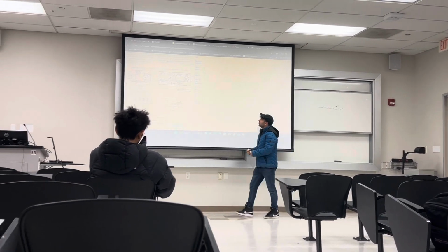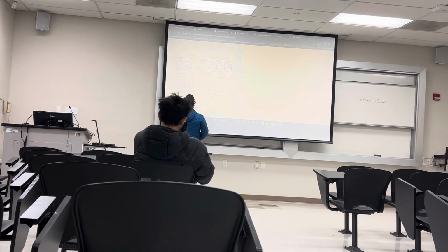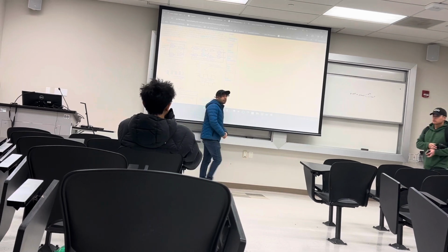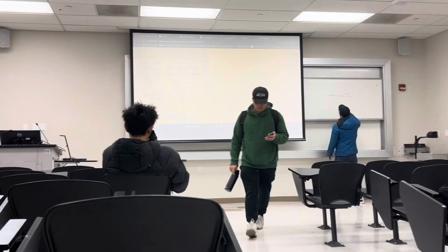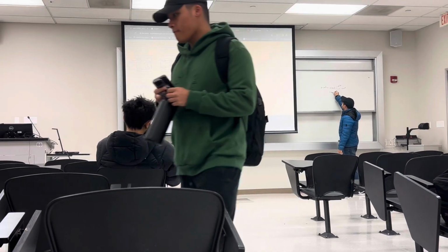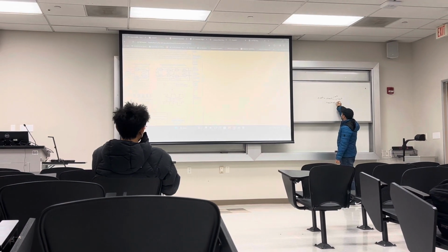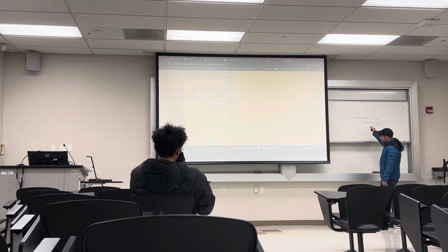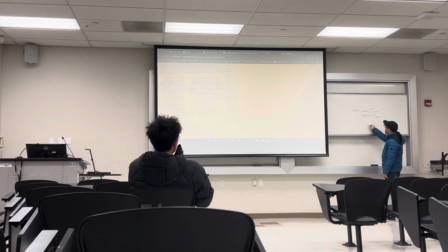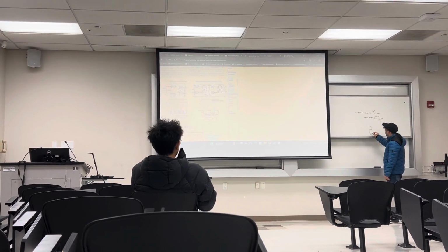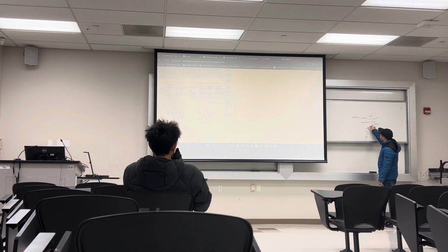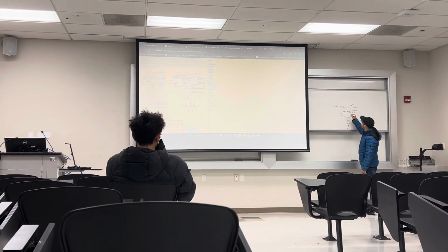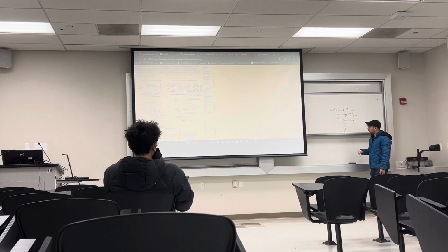The only difference is that here you also have some NAND gates with 3 inputs, as you see. The inputs of the JK flip-flop use 3-input NANDs. So based on the NAND that you designed, design the NAND gate with 3 inputs, and then design the schematic and layout. For example, if you have a NAND with 2 inputs, this is the output, and you want to make it 3 inputs.